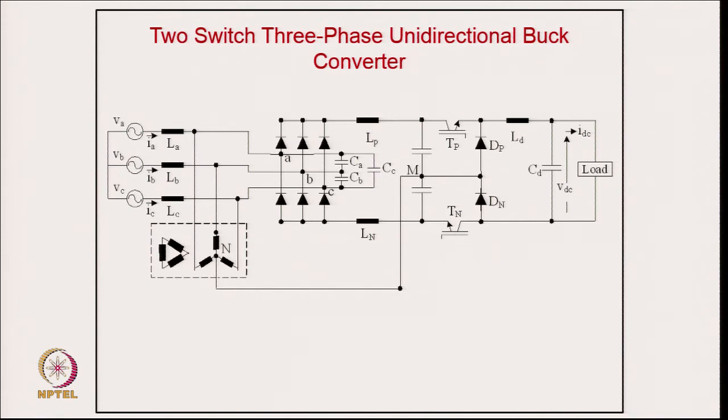But of course, we also use a 2-switch derived converter, similar to what we discussed for another converter with ripple injection, like the Minnesota rectifier, but this is for buck operation: 2 converters operating in buck mode for regulating the output inductor. For this ripple injection circuit you can use a zigzag, or you can use a star with a closed path for ripple injection with the delta circuit.